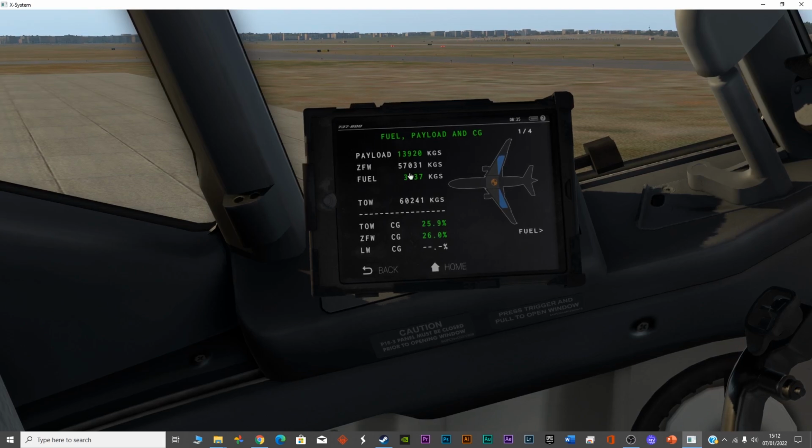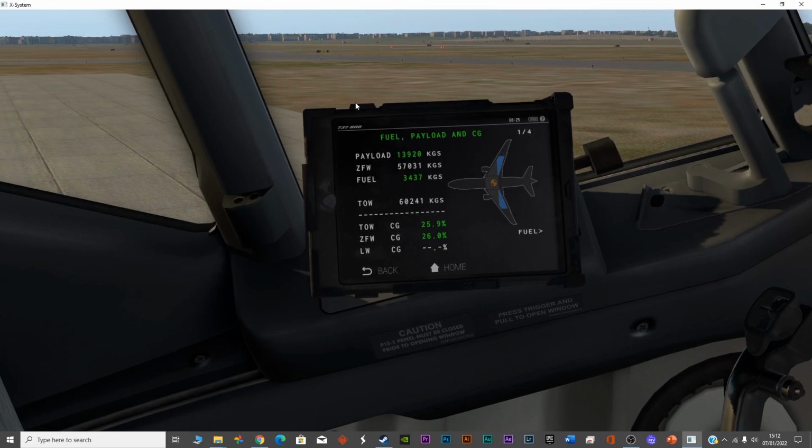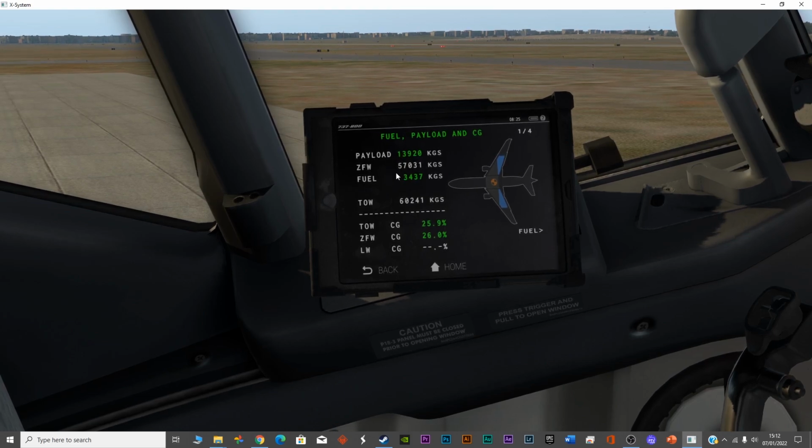So what you do is this, you can open your calculator. I'm using a calculator for this, not so good with the mental maths. So 60,878 as per the flight plan. This is the weight you should be carrying. Right now it's 57,031. Oops. So 3,847 kgs additional.